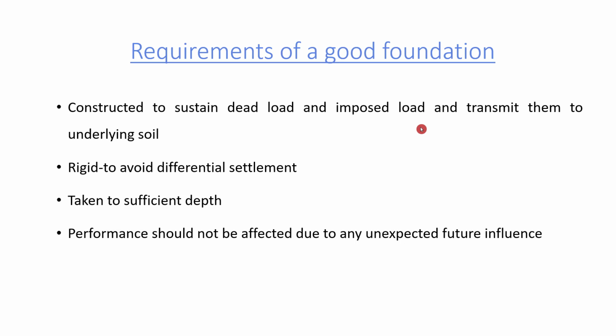Suppose that means throughout the life of the building, you are not going to keep the furniture at a constant place. You'll be constantly moving furniture by rearranging, and also there will be some functions in the buildings. There will be gathering. Sometimes there won't be any gathering. So all that differential or varying loads come under the imposed load, and the building self weight or the things which are made permanent will come under the dead load. So foundations are meant to transmit all kinds of loads coming to the building to the underlying soil.